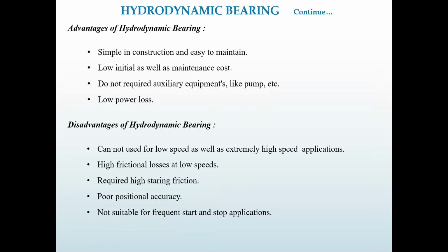As we are using grease, for example, the maintenance is very low and the initial cost of this kind of bearing is also very low. It doesn't require any external equipment like a pump or filters. Also, it has a low power loss.